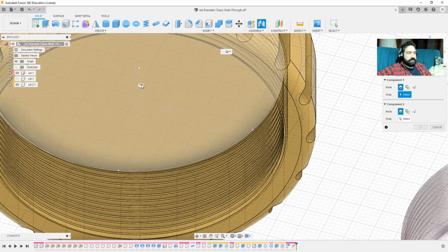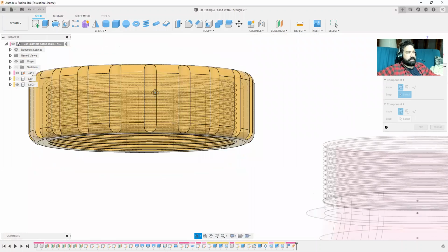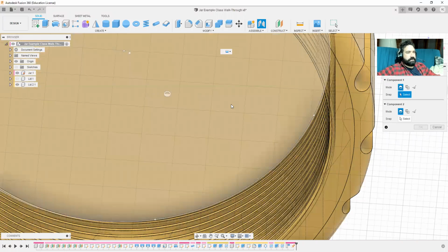And you'll see in the middle here, there's a square, but there's also that plus. Which one do I select? What that plus is referring to is actually on the other side, and it's really difficult to make sense of that. So what you can do, when you're moused over the plane you want to work on, is on Windows, press and hold Control. On Mac, press and hold Command. That locks your cursor selection to the plane you're currently highlighting.